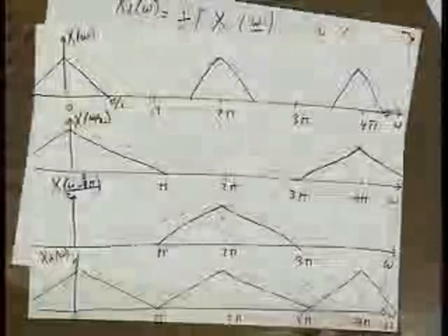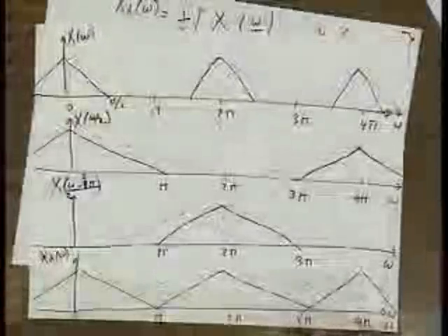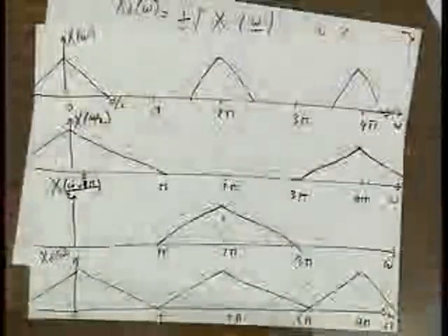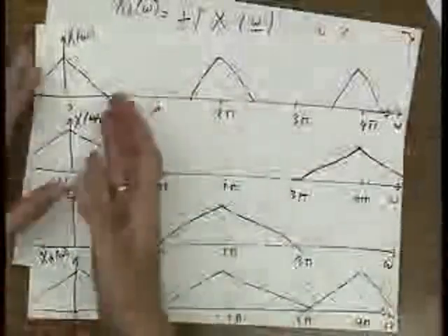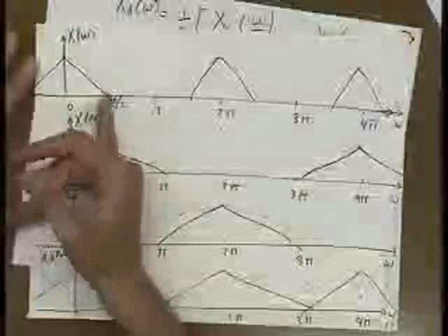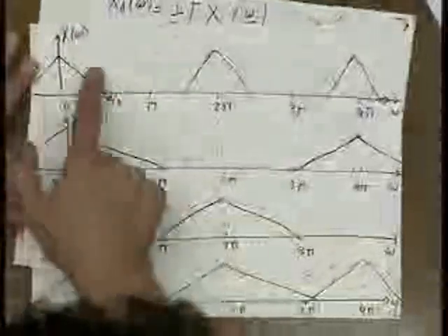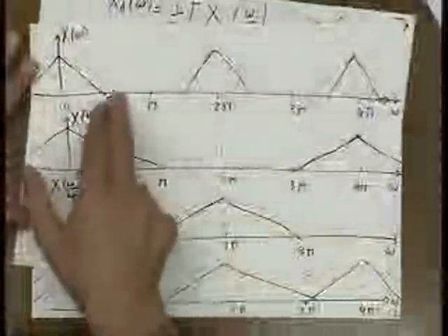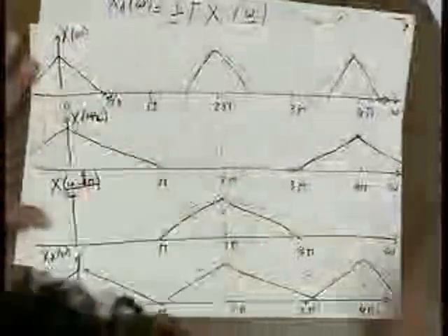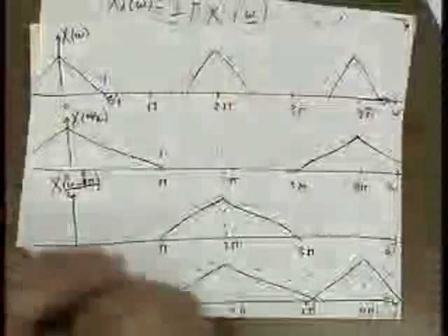Any time you do downsampling, just before you do that, because you're not sure whether you were critically sampled or not, the low-pass filtering doesn't harm you if you were not critically sampled. But if you were spilling over here and weren't ready to be subsampled, by just low-pass filtering it, you chop this off, chop this off, chop this off, and therefore you prevent further aliasing.